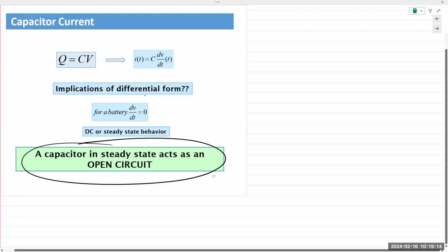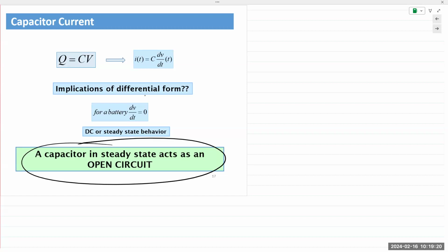Right? So you saw that in steady state, the capacitor behaves like an open circuit. You don't include or account for that resistor voltage. There's no voltage drop across that resistor because the capacitor reaches full charge. Open circuit, no more current is flowing through there. All of the voltage is across the inductor and the other two resistors, because the inductor behaves like a short circuit.